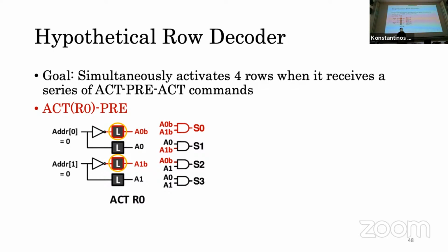main hypotheses. Okay, so they don't actually know whether it's because they can't activate the 4 rows at the same time, or if it's the timing thing you said? Well, they know they can't activate the 4 rows at the same time. Okay. That is the big issue. And that could either be because of the DRAM controller, or because there's some additional circuitry maybe that doesn't allow the violated timing parameters. That could also be a reason why you wouldn't be able to activate 4 rows. Okay, thanks. Anyone else?